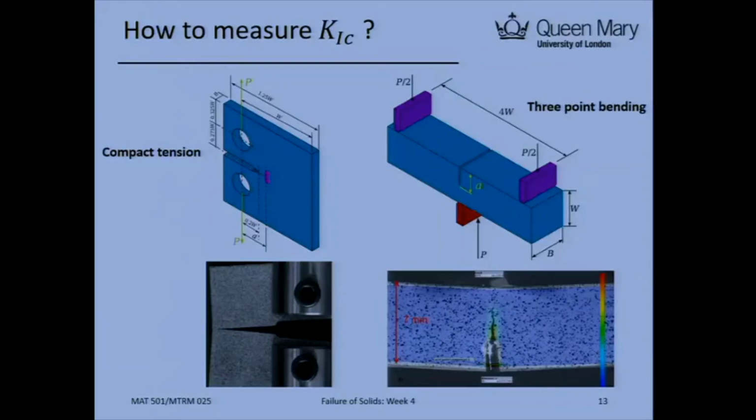You're right. Because in that case, the bending specimen in the bottom side is under stretching, so it's under tension. So you're actually applying mode 1 open loading, similar to the compact tension. You open the crack, basically as a mode 1 fracture.